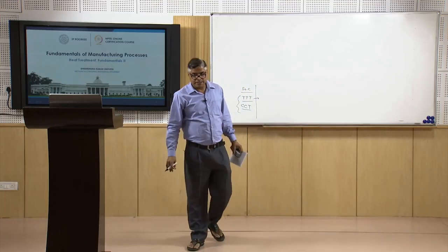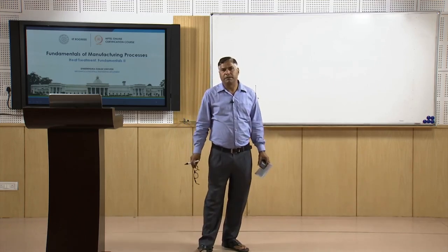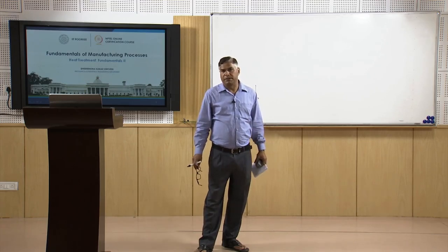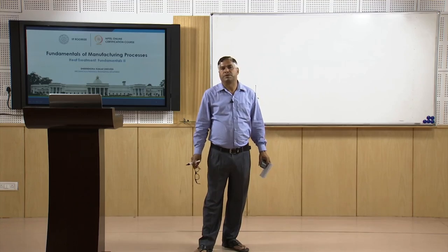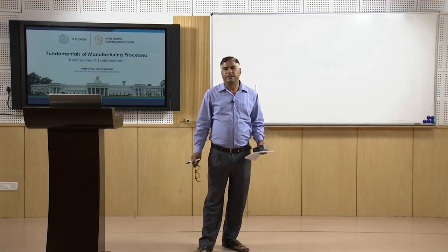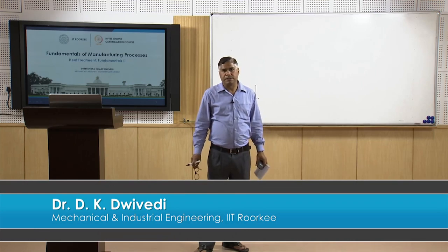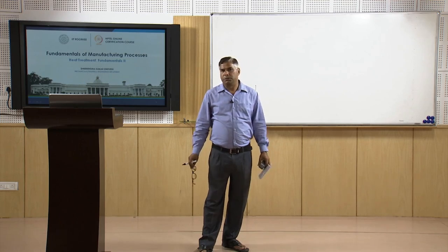So, now I will summarize this presentation. In this presentation I have talked about the metal strengthening mechanisms and the basic principles which are used for the heat treatment of steels. I have talked about the iron carbon diagram also, which can be used to find out how to identify the maximum heating temperature for the heat treatment of steels, based on the upper critical temperature limit in light of the composition of the steel.